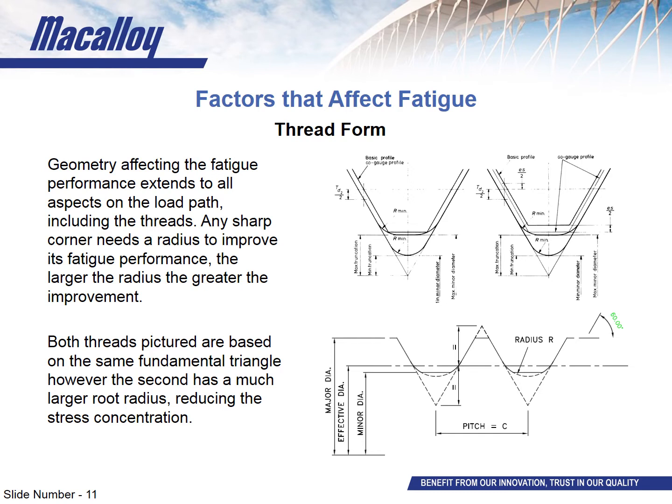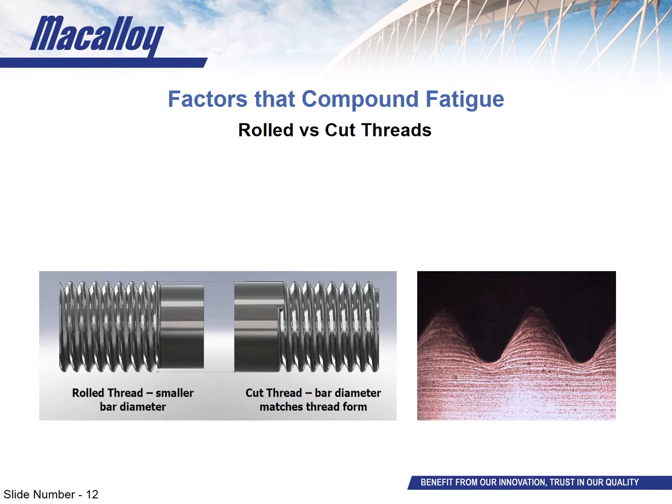The presence of a radius will lower the fatigue demands in any component if placed appropriately. The thread form is merely an example, but this extends to couplers or turnbuckles too. Another aspect that affects fatigue regarding the thread is actually how it's created.